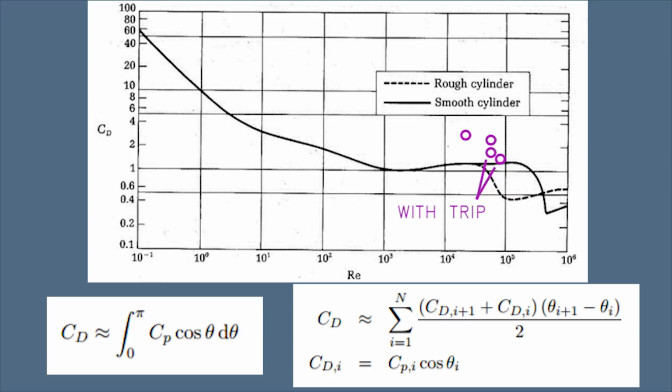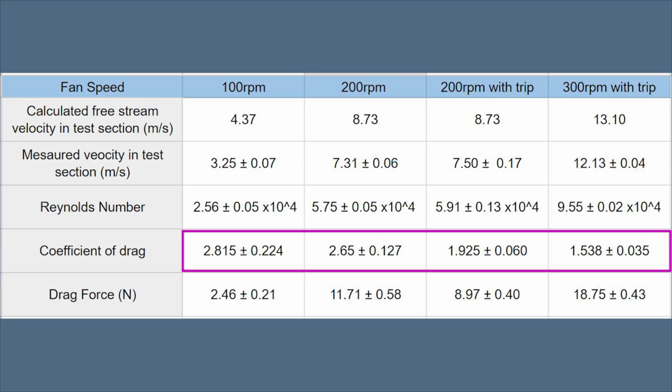There are various other contributors to error within the lab, such as dropping the cylinder, doors being opened and shut while data was being taken, changing atmospheric conditions, incoming air being drawn through the vertical opening before turning horizontal down the tunnel, and people moving around the lab during testing. All of these contribute to the eventual errors seen in our coefficient of drag calculations, and why our calculations are slightly higher than the theoretical empirical data while still seeing the same trends. Finally, the error for the coefficient of drag is carried over into the final error calculation for the drag force on the cylinder.